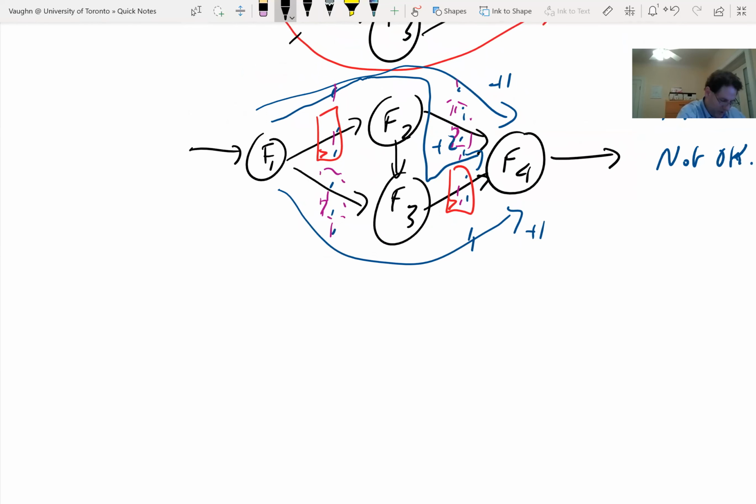Okay, so I'd cut that edge, and I'd cut that edge, and I'd cut that edge, right? So then I've added latency there, and latency there. It fails my most fundamental test, because it didn't add the same. So I think you're asking, what if I did a cut here? Going back to the more fundamental test of did it balance my latency, it fails that. And that's the really fundamental test. Now it appears that it disconnects my inputs from my outputs. So you're saying, why does that cut not work?